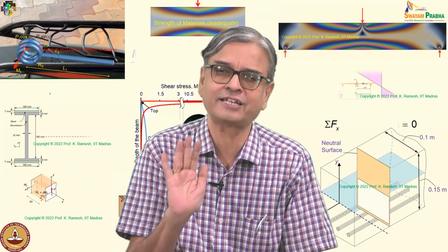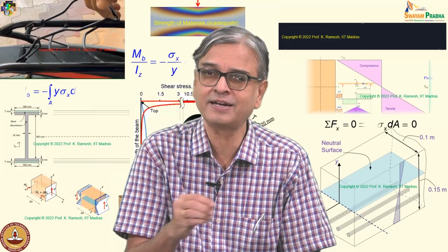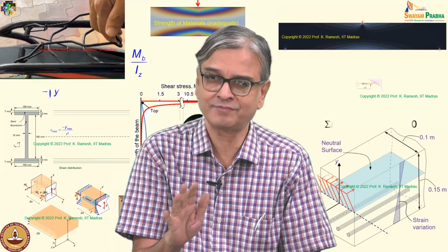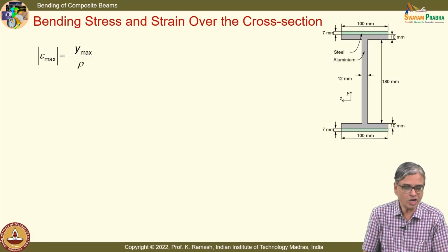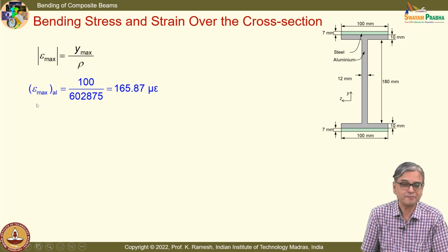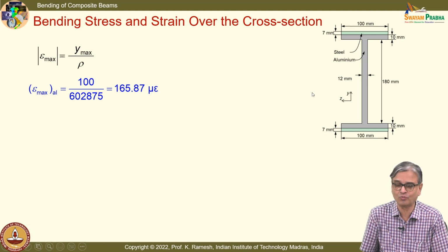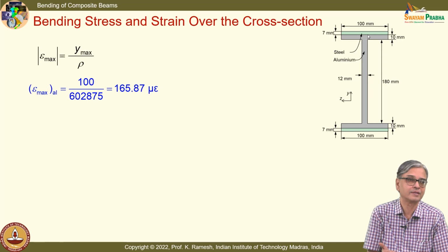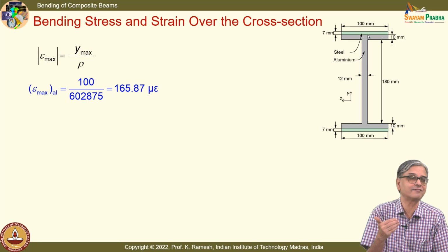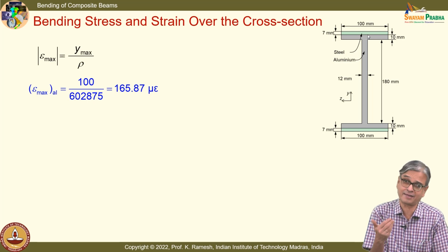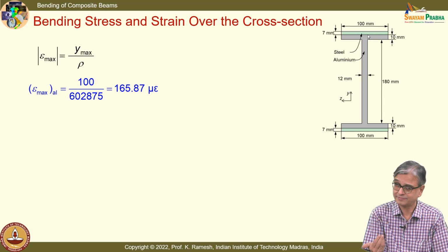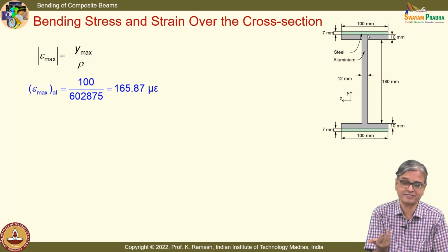It is better to learn that here. We have learnt it very systematically with proper sign convention. And when you solve problem after problem, you want to find out what is the maximum strain. You want to know the distance from the neutral axis to the fiber which is farthest away. Here I have a symmetrical beam. If I have a T section, one side will be nearer, another side will be farther. So, the farther stress can be compressive or tensile in a section like a T section.